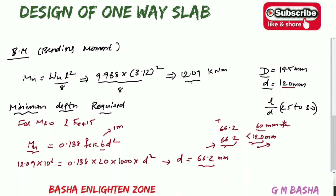If we were using 60 mm instead, at that time you would have to change it and restrict that value to 66.2, and based on that go for a trial section again, or restrict that value to 66 and take down the clear cover and effective cover, and design the slab based on that. Because the slab requires a minimum effective depth of 66.2, but we provided more than that, so it is safe here.